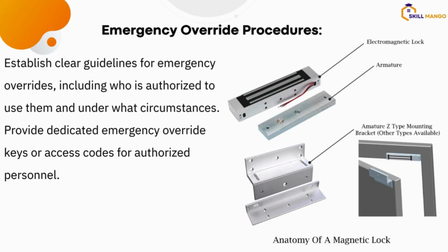As we all know, this maglock uses a magnetic lock and the armature. They connect together, so nothing can separate them. No matter how strong you are, you think you can open them, you cannot force them open. So it's important to understand this fact and know that when you cut out the power supply to the system, the door will disengage. The power will make sure that the maglock and the armature disengage and all the doors will be open. All the doors will be open, so people can go out and escape the building.